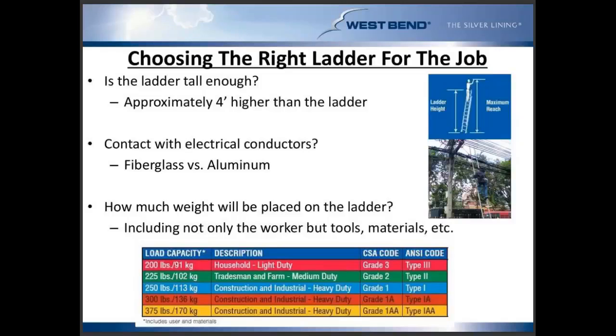Another consideration is, do we have any electrical conductors in the area? If so, then we definitely want to go the fiberglass route, being that it's an insulated type of ladder as opposed to aluminum, which is a conductor and could complete that circuit if it were to come into contact with those electrical conductors. The picture to the right illustrates a scenario where that could likely happen.